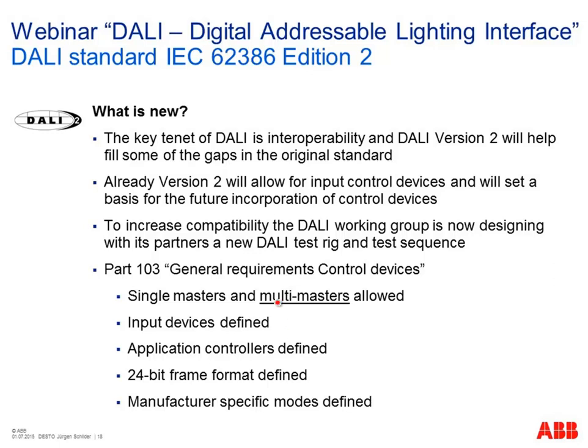And in this part 103, there's also described the single and multi-master system, which is new. At the moment, the existing DALI system is based on a single master. What is a master? A master is a component which can actively send by itself a command, a telegram, on the DALI system. For example, our KNX DALI Gateway is such a component. So it can send directly. Or if you have a standalone DALI system, any sensor, any group or scene controller, any touch panel could be a master, but only one master was allowed in the system up to now.